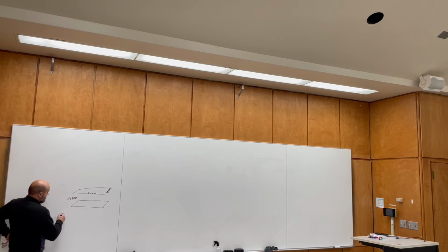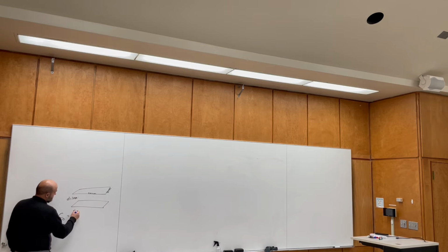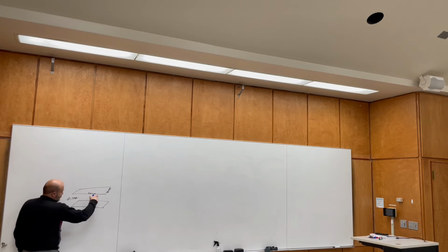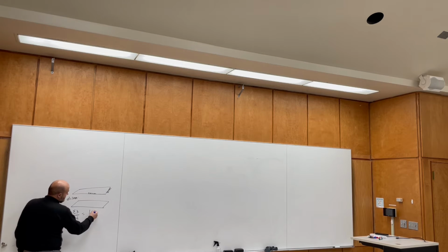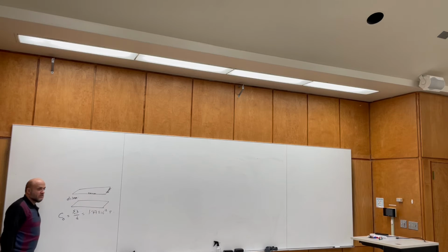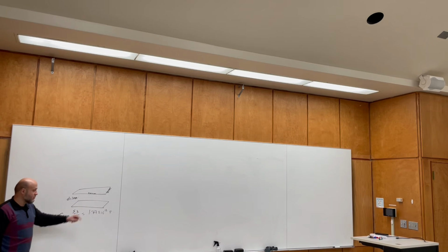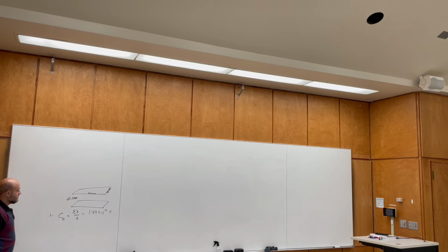First thing we asked about C, and we'll call it C0, because we have air between the two plates. And this is epsilon 0 area over D. Area is 0.2 times 0.1, epsilon 0 is 8.85 times 10 to minus 12, and D is 1 times 10 to minus 3, and we got 1.77 times 10 to the negative 10. You can look at the example we did yesterday, or you can do the numbers and get this answer.